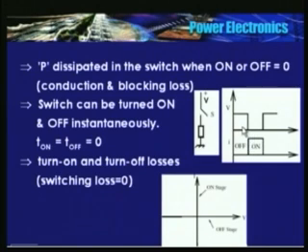So what is the consequence? If the changeover is instantaneous, the time taken, T on, that is equal to T off, both are 0. Therefore, the loss taking place during on time and when it is being turned off is 0. I will repeat, the transition from off state to on state is instantaneous.